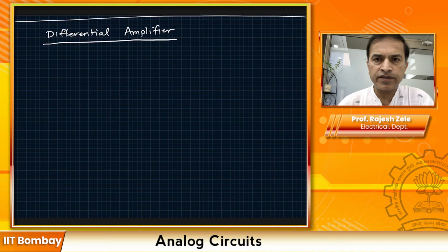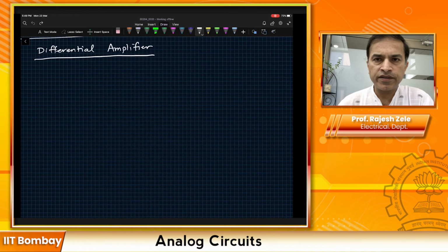Let's say there is a terminal P and terminal N. What you would really like is, between the two terminals P and N, the difference between those two we would like to amplify by a large value. However, anything that exists on terminals P and N together, common to both those terminals, VP and VN, like a large hum, we would like to subtract it out.